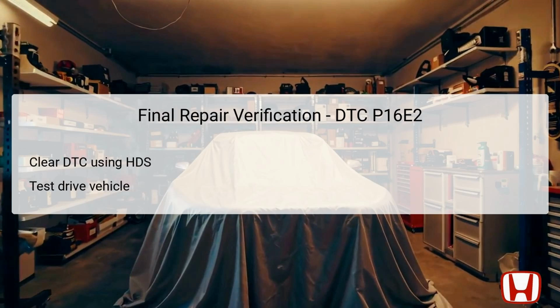After addressing the underlying issues and completing the troubleshooting for DTC P16E2, it's time for final repair verification. Start by clearing the diagnostic trouble code using the Honda Diagnostic System, HDS. This action resets the vehicle's onboard computer, allowing it to remove the error code from its memory.